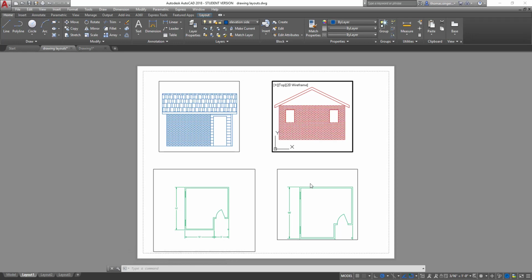So there are also some tricks to alignment. Now that we have a scaling factor, and the blue and the red side images of the object are both the same scale factor, let me double click out of the viewport. Remember, we're working over the object right now. I'm going to draw a line. What's nice is that I can actually connect to the objects that are still inside, and we're going to draw a line across. Now why did I do that? Well, this line now represents the bottom of this object.